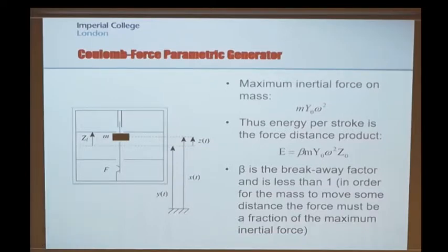And that really, again, is about optimizing the force. If you make the force too big, then you'll never be able to push the device off the frame. It'll just stay glued to the frame. If you reduce the force a little bit, it'll push away. But again, if you make it too large, it might come back to the same side, and you do a bit of work and then you give it back, and you don't generate any power. What you want is the device to push off one side, the mass to fly all the way, and to hit the other side, at which point you can capture the energy.